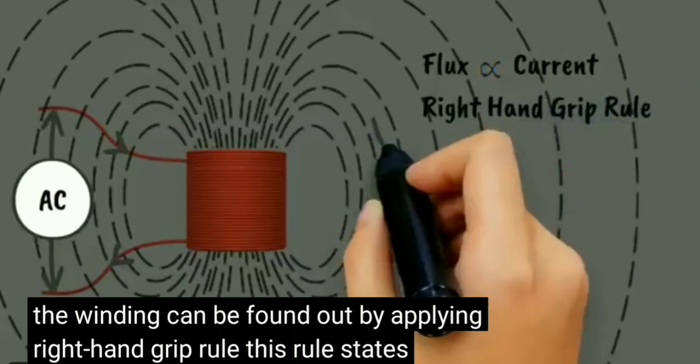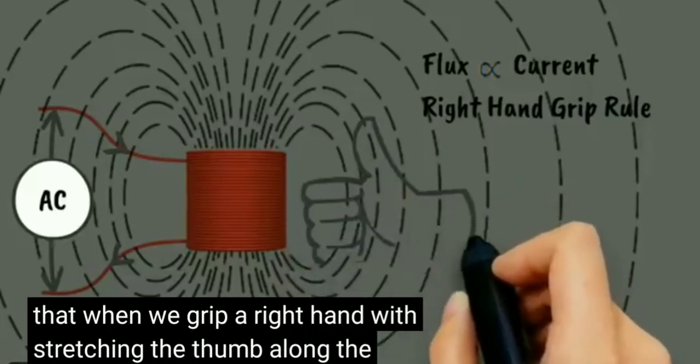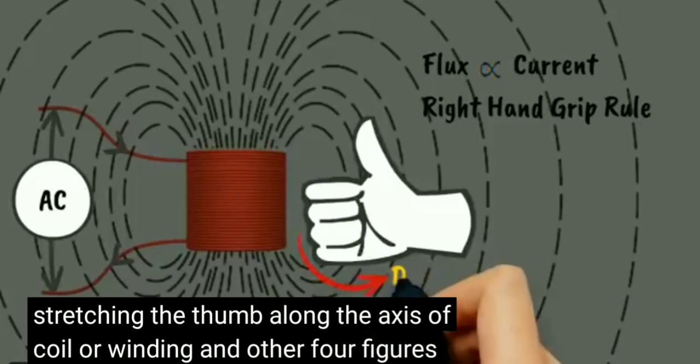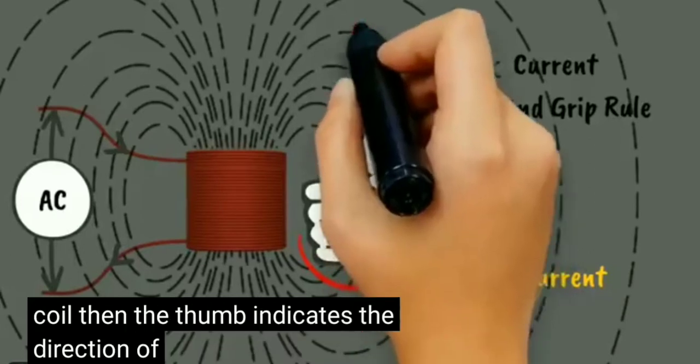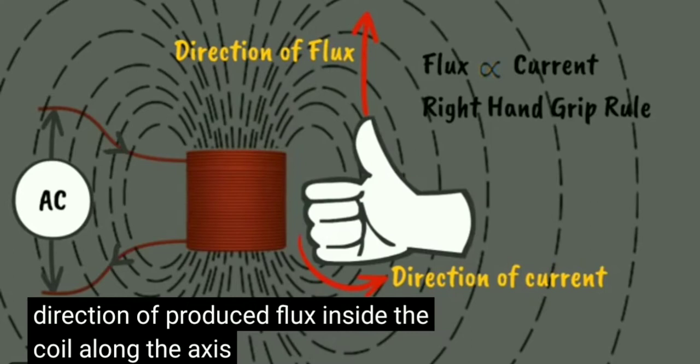This rule states that when we grip our right hand with the thumb stretched along the axis of the coil or winding and the other fingers along the direction of current in the coil, then the thumb indicates the direction of produced flux inside the coil along the axis.